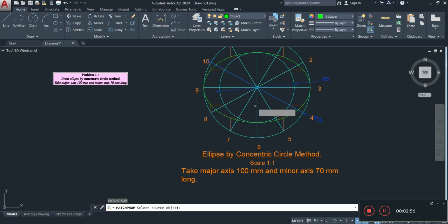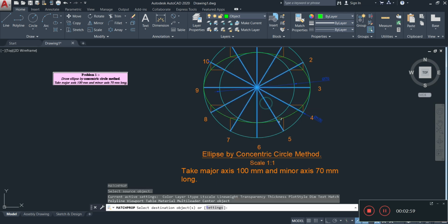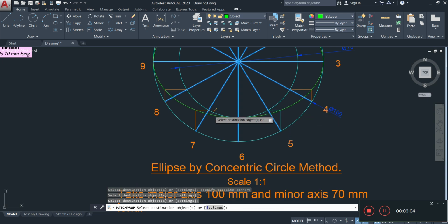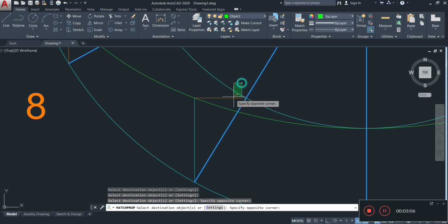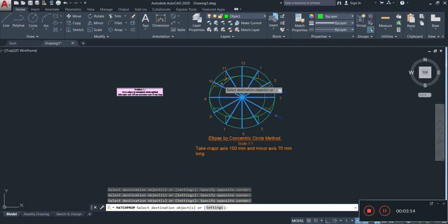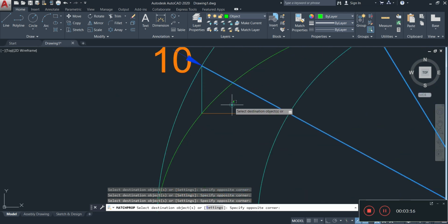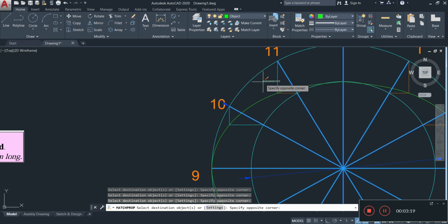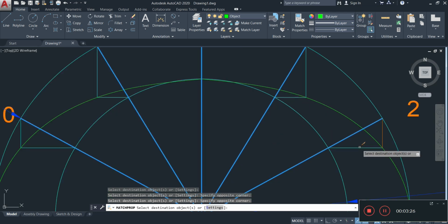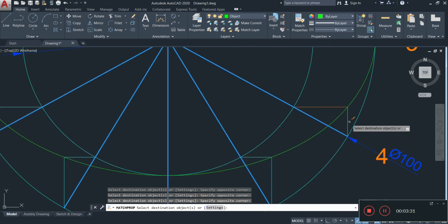So I'm going to move some things around. So for example, you remember these lines here, these are supposed to be on your construction layer. Alright, so those are construction layer. Alright, and it pays to have these on the relevant layer with your line weight all set up, because it will make a large difference when you're printing your SBA. Because when it comes to contrasting between the different parts of the drawing and the importance, that's where your line weight will come into play. Alright, unless you're printing in color, then you might get away with certain things.